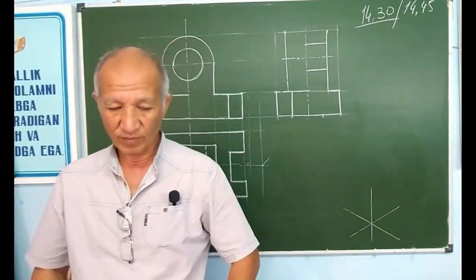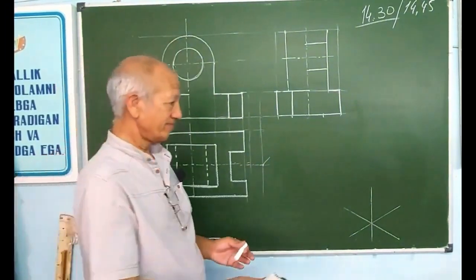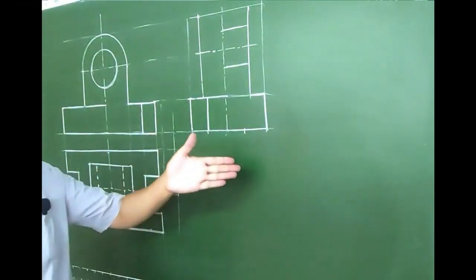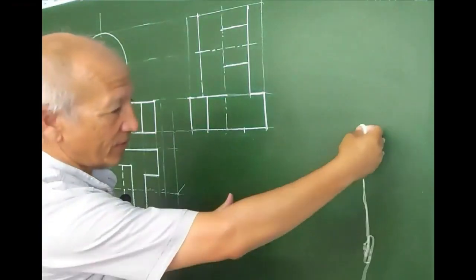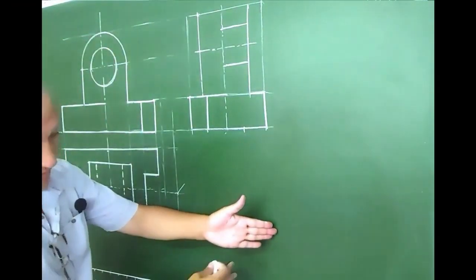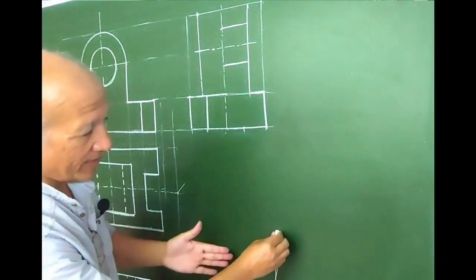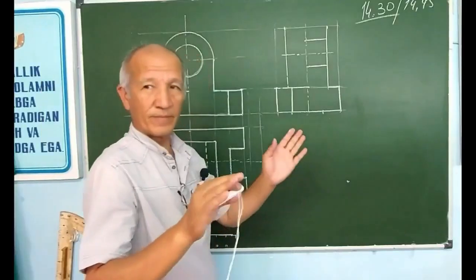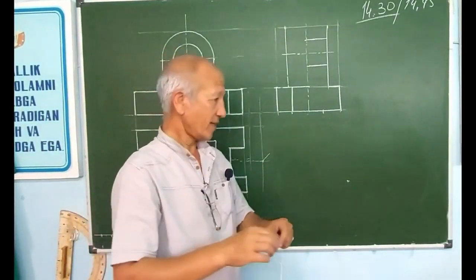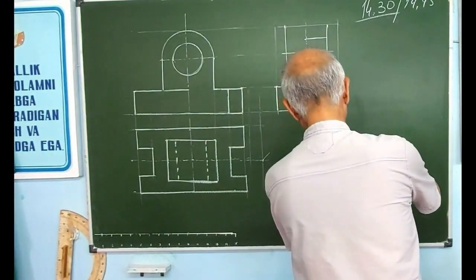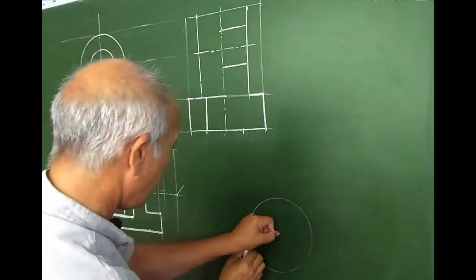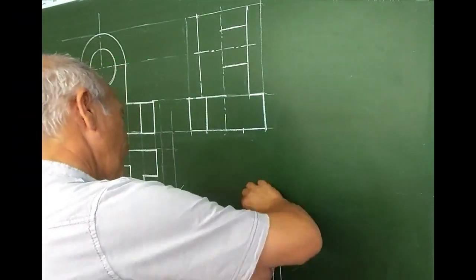This is actually quite convenient when drawing on that sheet. When you're thinking about the center, if there's a midpoint, know that half of it goes this way and half goes that way. If there's a small cut section, you can just estimate it. From here, you can draw a circle with any radius you want. The radius doesn't matter. After you've found the center and drawn the circle, what should you do next?